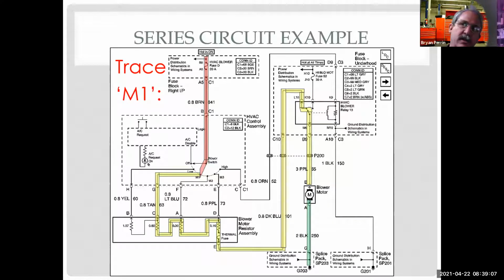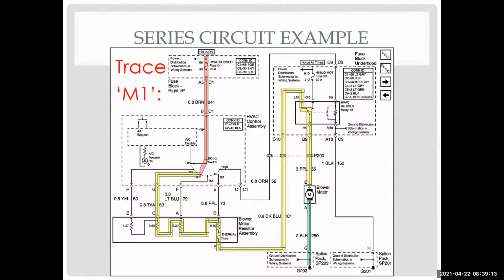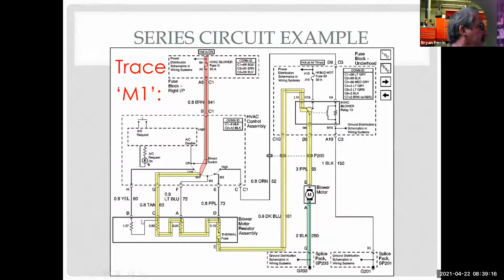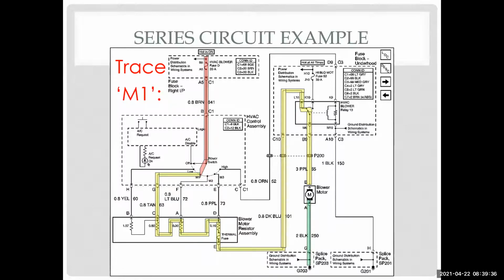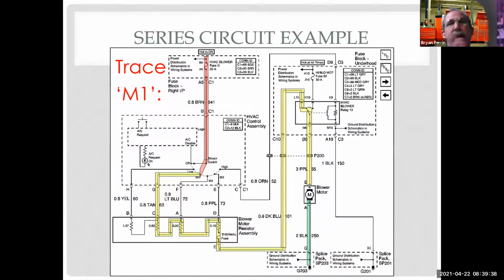System voltage? Why would I have system voltage there? There's no load. Okay, well, you're half right. Actually, you're 2/3 right. So I would have system voltage at B. There is a load here, right? Because if I come from here back this way, there is a load. However, because it goes to an open circuit and there's no current flow, we won't drop any voltage around the load. That's why I said you're about 2/3 of the way there, which is great.